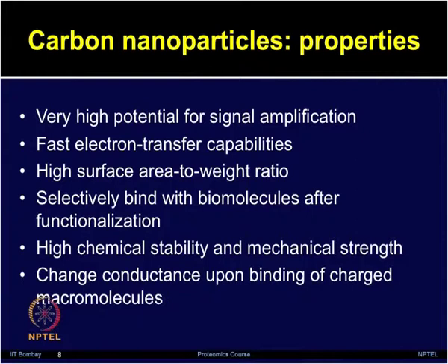They can selectively bind the biomolecules after functionalization, and this selective binding with very high sensitivity is the key advantage of using these nanotechniques. They exhibit high chemical stability and mechanical strength as we discussed earlier, and the changes in the conductance upon binding of the charged macromolecules are monitored for these binding reactions.